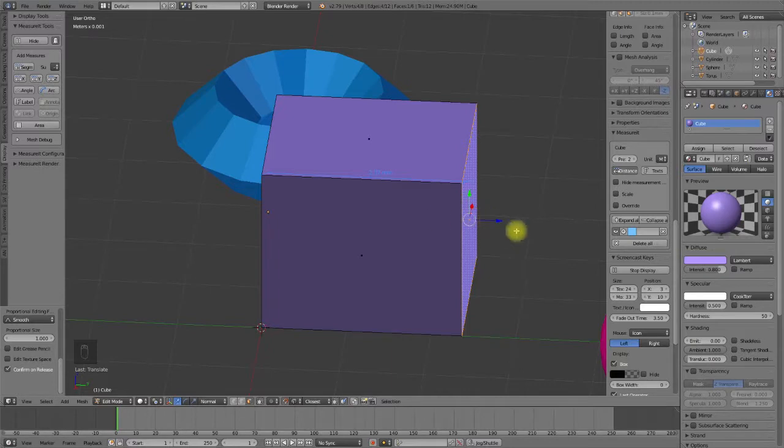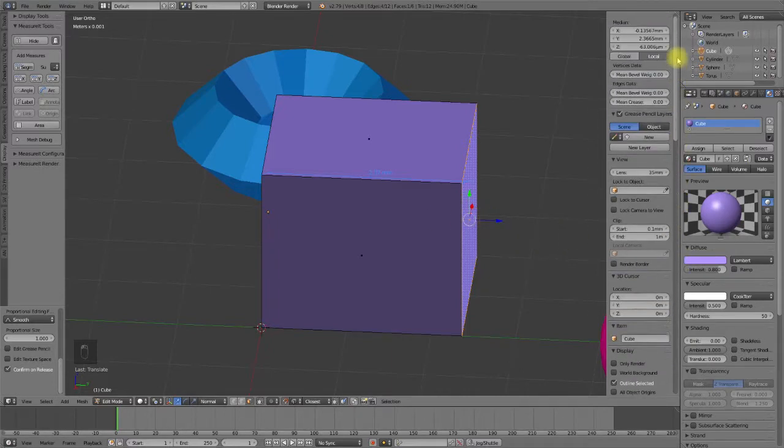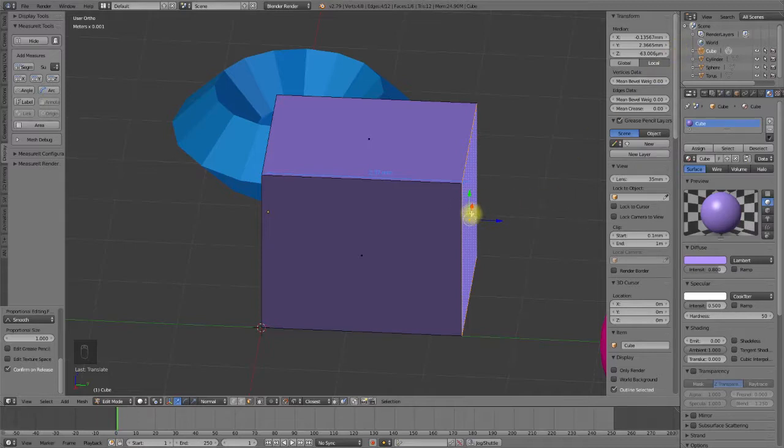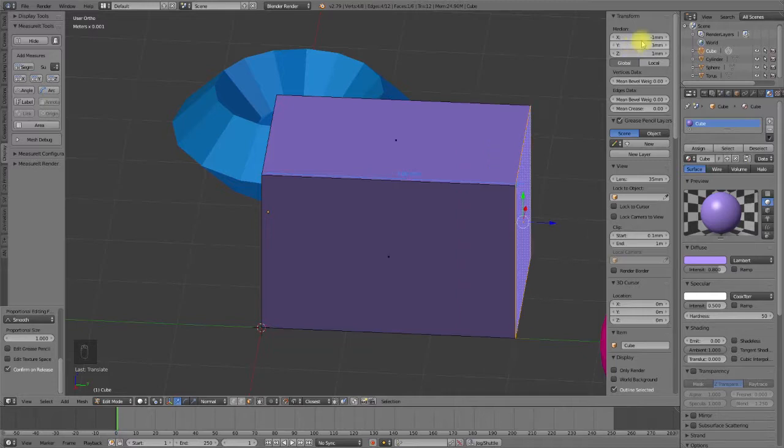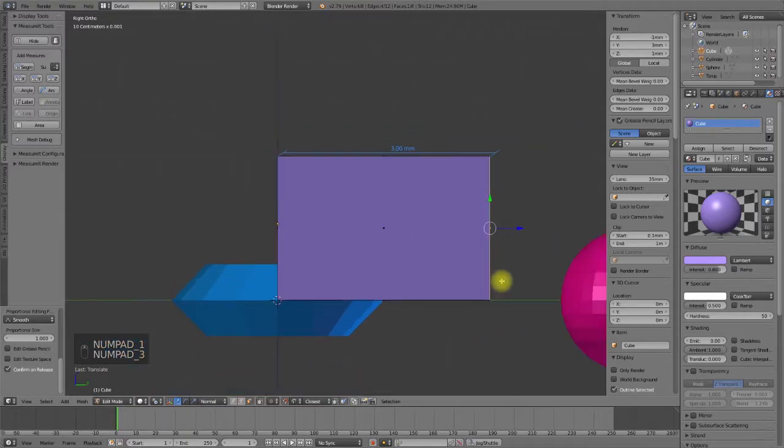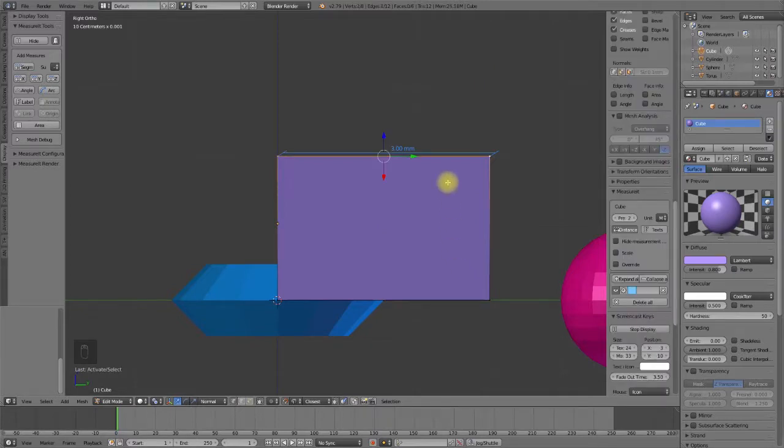You also have the possibility to change the global coordinates of the model part. For example, if I change to the global coordinates and set the position 3 on the y-axis, I can exactly move that model part, the face, to the position on the y-axis. These are some short examples of how we can change the overall size of the object or move individual model parts with precision.